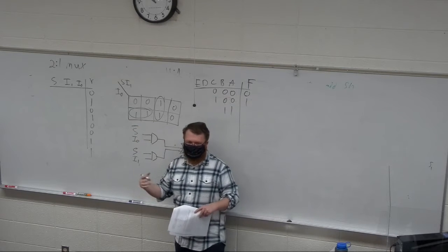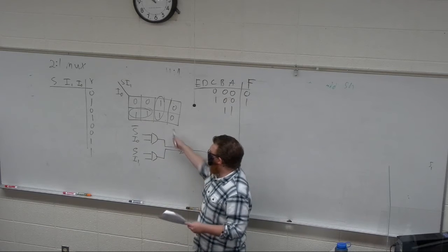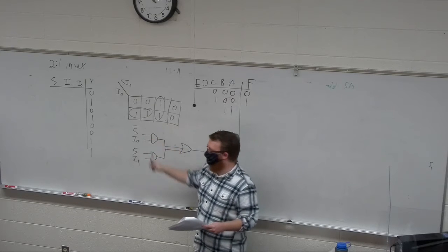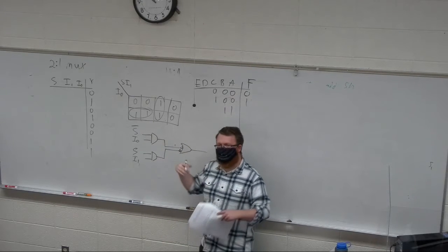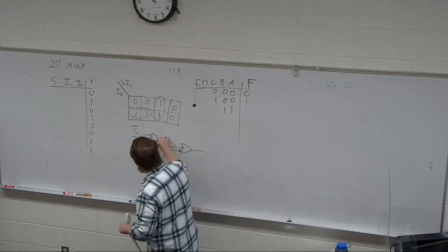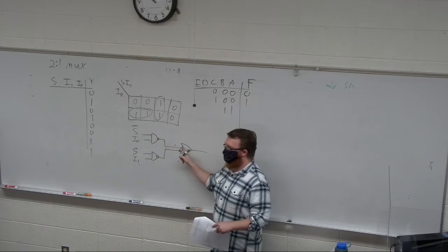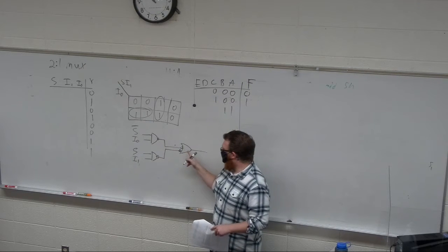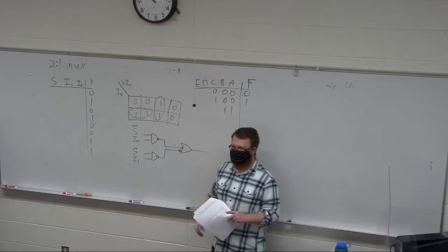Now they implement this as NAND gates because we like these universal gates. Now, the nice thing about sum of product implementations is they turn into NAND gates really, really easy, right? I just add inverters here and the inputs. And if I want to undo what I just did, right? So this just broke the circuit. I can fix the circuit by re-inverting it. So I invert, de-invert. This is the exact same circuit. It's just two inverters in the middle. But it also is nice because this is a NAND gate and these are NAND gates. Now I have universal gates. Done.